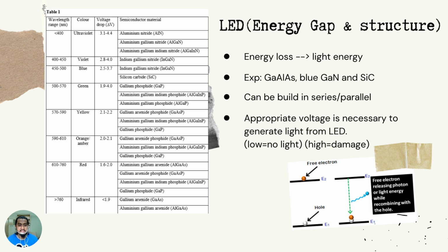The LED chips consist of light-emitting semiconductor material as well as a lead frame with both cathode and anode, onto which the die is put. The latest generation LED is based on gallium aluminum arsenide semiconductor material built as a double heterostructure on a transparent substrate, and it has shown promise in plant growth and morphogenesis investigation. LED designers have also employed laser diodes with visible spectrum outputs to create high brightness LEDs.